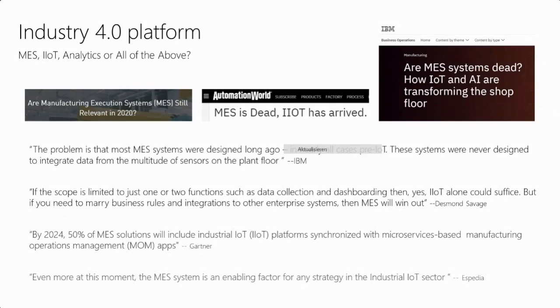Generally, on factory floors, we will have PLCs. PLCs are nothing but programmable logic controllers. This is something which is very, very inherent to us as electrical and electronic engineers. Using PLCs, we will send production related data immediately, using Siemens or some other PLC controllers. We send it to the MES system. The MES system will track what is being produced on the production floor on a real time basis. Let's say that we are producing a shoe.